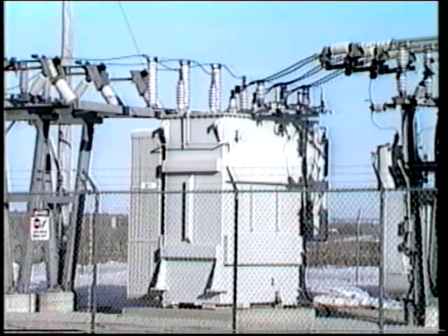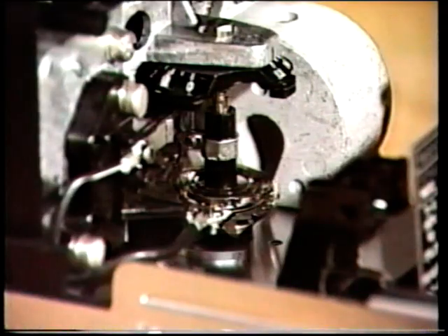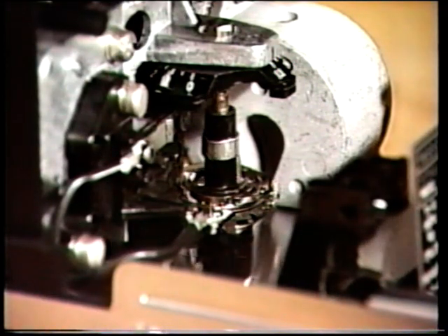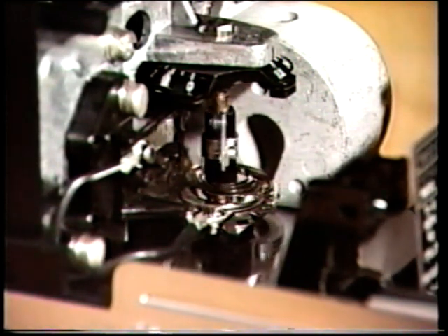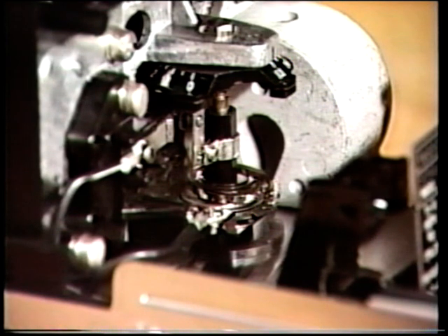For smaller transformer banks in the sub-transmission and distribution systems, a simpler differential relay without harmonic restraint may be used. The operating element consists of an induction disc. This operates quite slowly, about 0.1 seconds, so it will not be responsive to the short-term inrush current. In yet another method for preventing tripping due to inrush, the operating coil of the differential relay is desensitized for a few milliseconds when the primary breaker is closed.